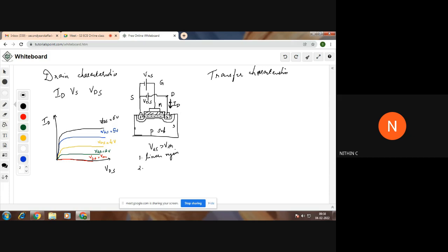So this will be the graph. That is when we increase the value of VDS. The x-axis is actually showing the increase of VDS. VGS equal to VTH is the condition where, whatever be the value of VDS, the value of ID is 0. That's why the initial red line is on the x-axis, there is no ID value.